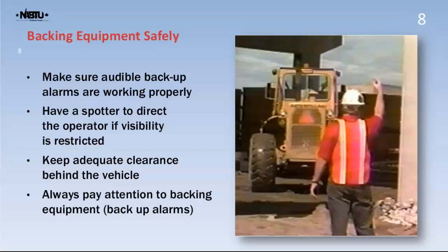The second point there is have a spotter to direct the operator if visibility is restricted. If the operator can't see behind them, they're going to need to have a spotter or a person that's waving them back and showing them the direction to go. If you're that spotter, you're focused on the vehicle that's backing up towards you, right?